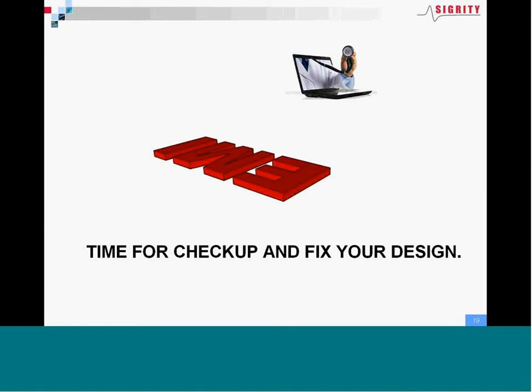Yes. In the optimization process, basically the tool first sets up EMI observations everywhere on the cavity, on the power plane cavity, and also sets up an EMI capacitor candidate port everywhere on the plane. On the port, the tool will also extract the loop inductance and the loop resistance of each EMI capacitor candidate, and then do the optimization. During the optimization, the tool will go to a capacitor library and test a lot of capacitor types in each location. So we do 100,000 capacitor tests or iterations until we reach the best solution that can give the optimal solution.